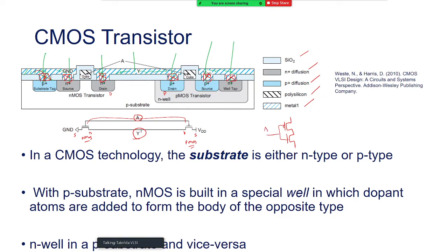If you remember, A, output Y, VDD, and the ground, right? That was drain, source, and the drain. So drains were together, so I call it Y. Gates were together, I call it the input, right?